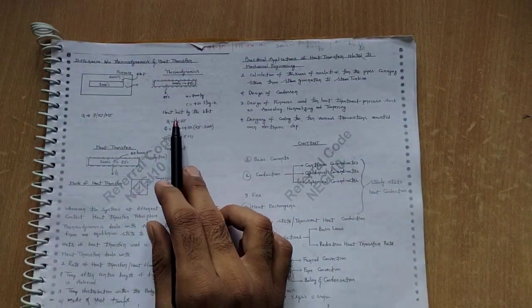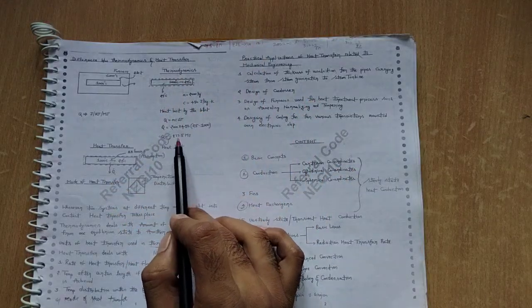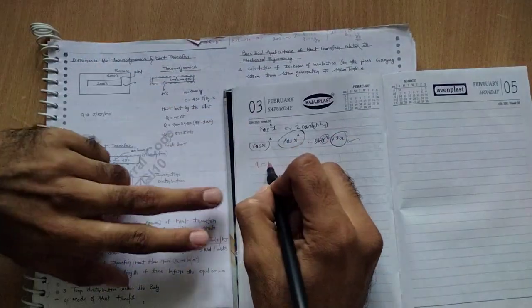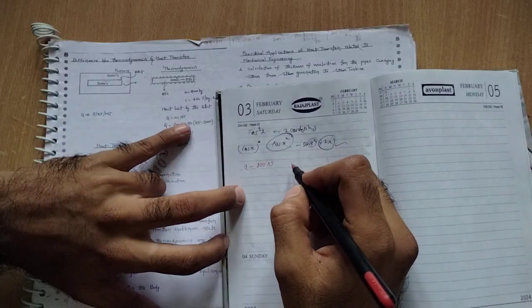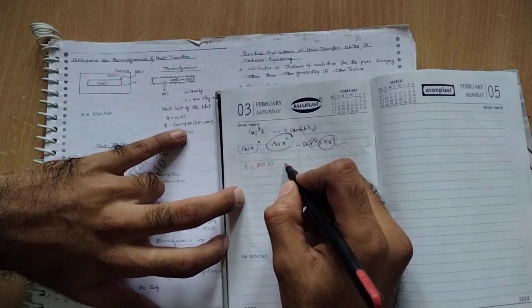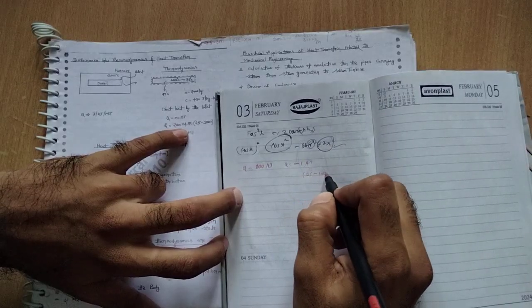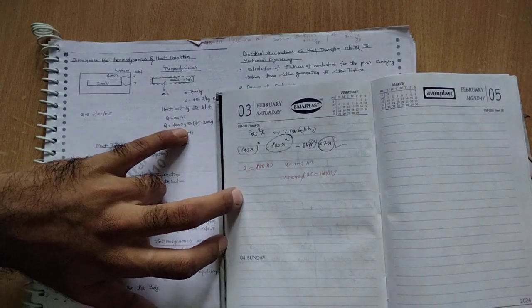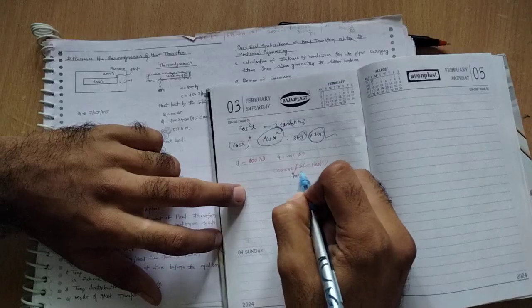In this example, the heat lost by the billet, in thermodynamics, is Q, say 87.5 megajoules. Q equals m c delta T, with temperature 25 degrees Celsius minus 1000 degrees Celsius, mass 2000 and specific heat 450. So it tells about the heat, but time is not involved.